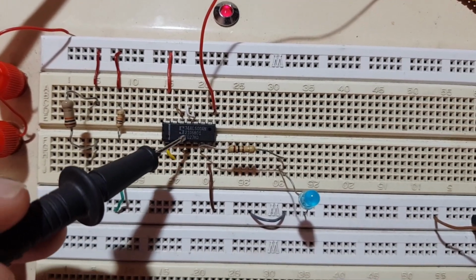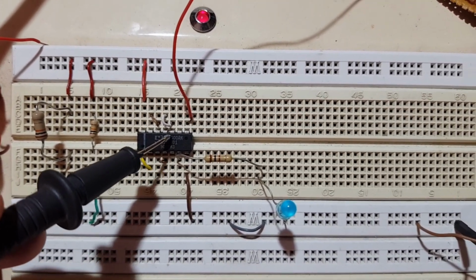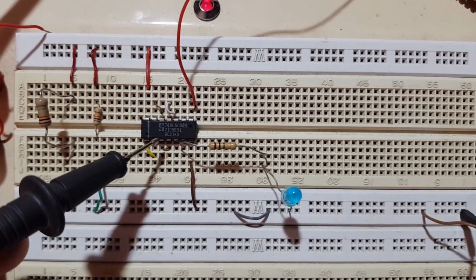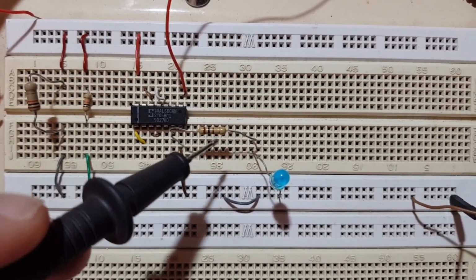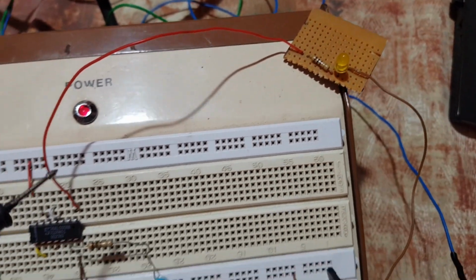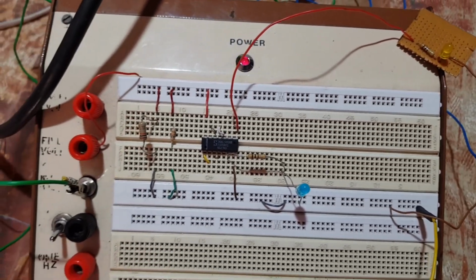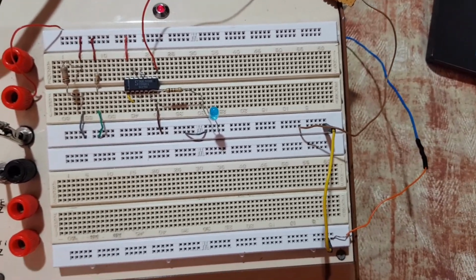You will see here as well that I have connected here pin 13 and 12, pin 11 and 10, pin 1 and 2, and pin 3 and 4. And then here's my pin 6, which is the output to the blue LED, and pin 8 here is the output to this yellow LED to make it easy to follow along. Okay. Next, we can put in our wires.